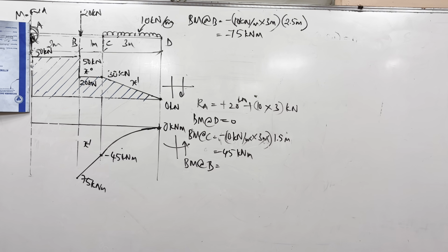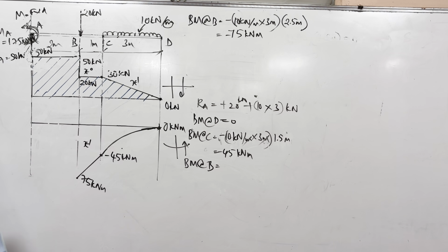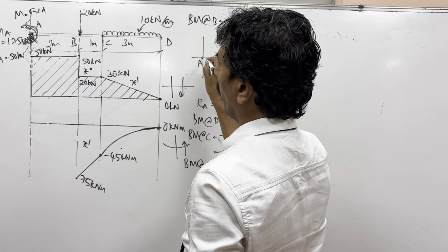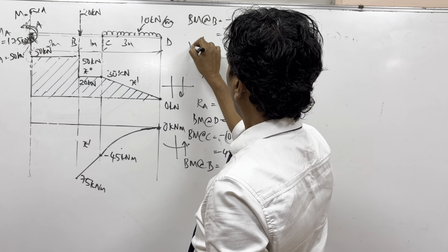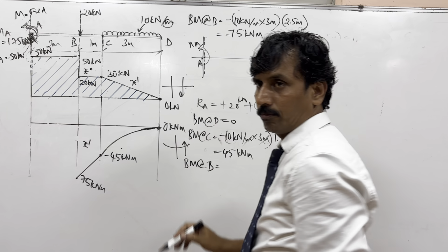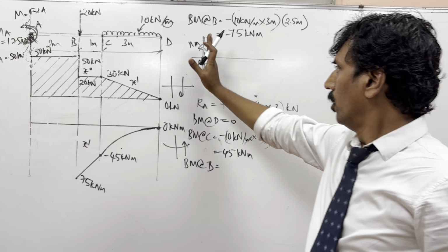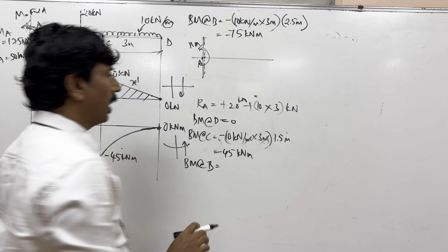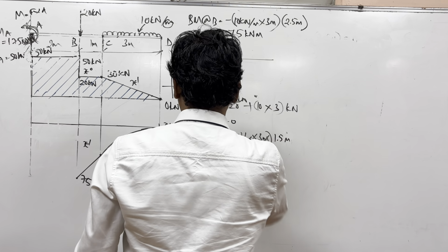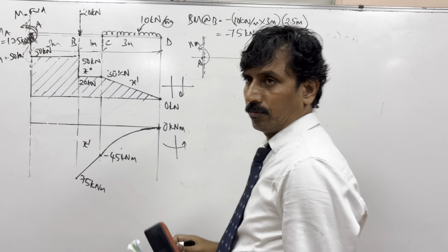finally at this point, if you want to calculate, you should calculate wherever there are moments. At A there was a moment, MA. What I will do is try to calculate just on the right side of this moment. So finally it will become 0 at this point. Before this point, I will try to calculate. I think in the case of cantilevers, people feel it difficult while calculating moments at this point.